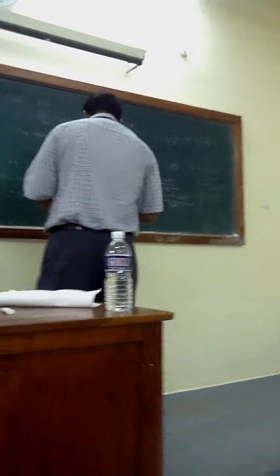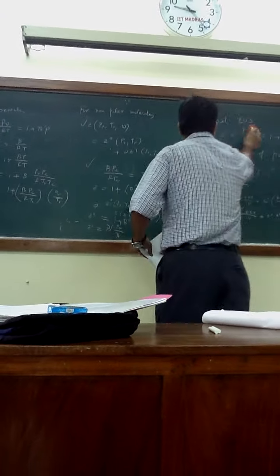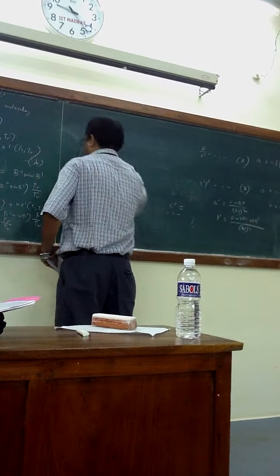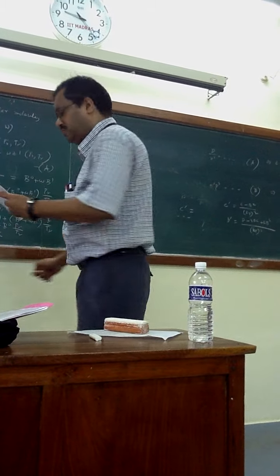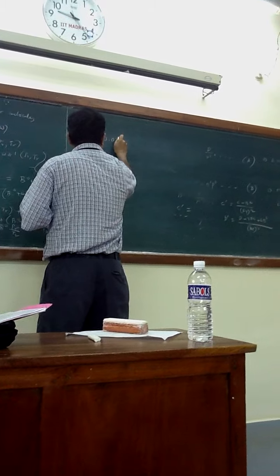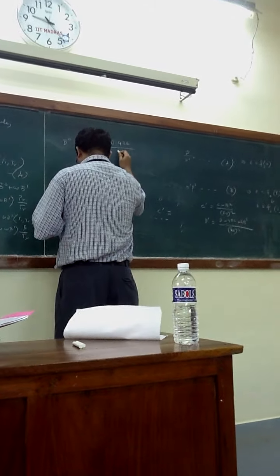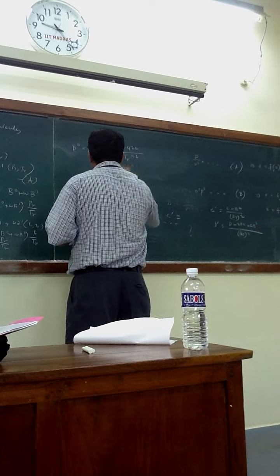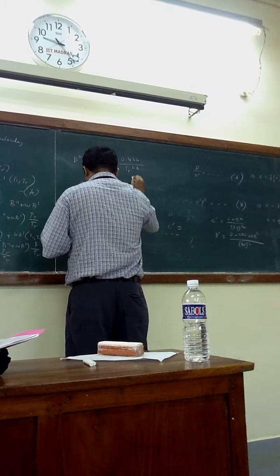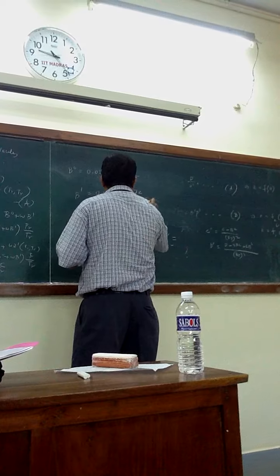And B0 and B1 are given for some of the materials, so you can take it down for one of the example problems. B0 is given as 0.083 minus 0.422 divided by TR to the power 1.6, and B1 is 0.139 minus 0.172 divided by TR to the power 4.2.